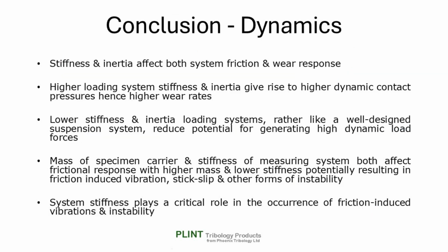Thinking about the dynamics, stiffness and inertia affect both system friction and wear response. In the case of load application, higher stiffness and inertia typically gives rise to higher wear rates, including fatigue-induced wear mechanisms such as rolling contact fatigue. This is because higher stiffness and inertia give rise to higher dynamic contact pressures. Lower stiffness and inertia systems, rather like a well-designed suspension system, reduce the potential for generating high dynamic loads.